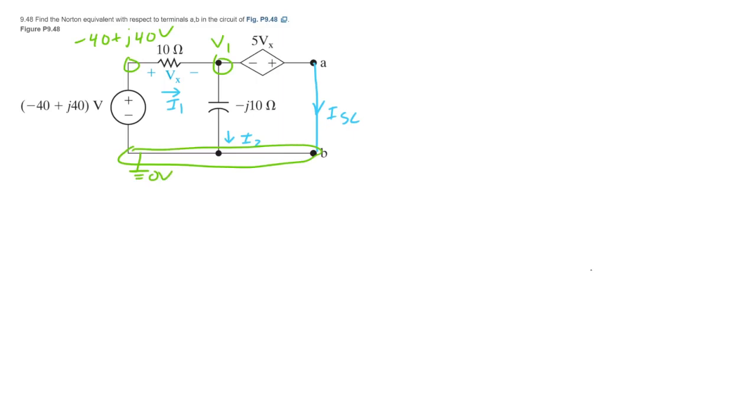Okay, so that's going to make our equations KCL: I short circuit plus I2 is going to equal I1. In other words, we could say I short circuit is I1 minus I2. It's the same equation, just a different form, because we're going to need to know I short circuit ultimately.